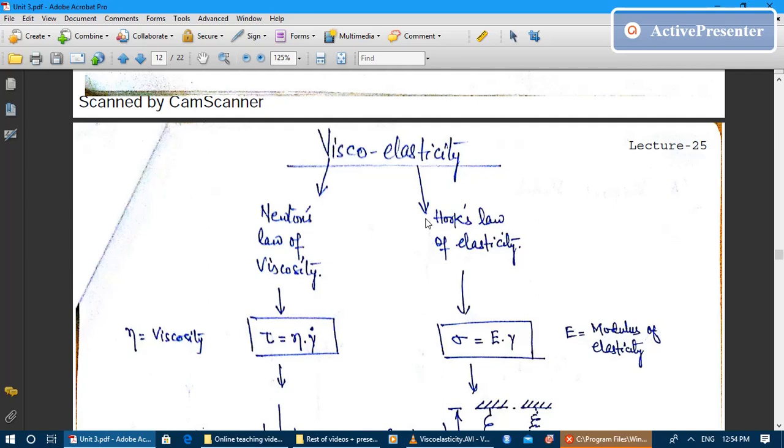So the energy is absorbed in the material in terms of a very slight increment in the bond length, and just upon the removal of the load the polymer or the molecule will basically retain its original bond length, and in that course of action the length of the polymer, which has increased because of the stretching, delta L, will come back to its original length L. Okay, so this is the explanation of how the elastic part and the viscous part of the polymer are contributed by the primary and secondary bondings.